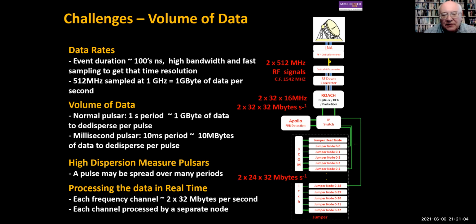One of the final challenges that we've got to look at for pulsar timing systems is the increasing data rates. We have an exercise after this lecture, but it will talk about bandwidth, digitization of data, how much information do we have available. But for example, for the Lovell telescope, we have an overall bandwidth of 512 megahertz. We sample those at a very high frequency rate, corresponding to the observing frequency on the Lovell. And that generates 1 gigabyte of data per second, just for a single polarization.